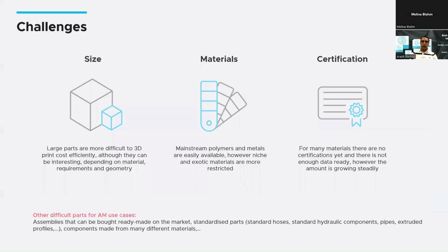Of course, if you are using 3D printing, or you are going to use 3D printing, there are certain challenges that you also have to take into consideration. Size is a topic you generally have to pay attention to. There are certain geometrical limitations in 3D printing based on which material or which technology combination you are using.